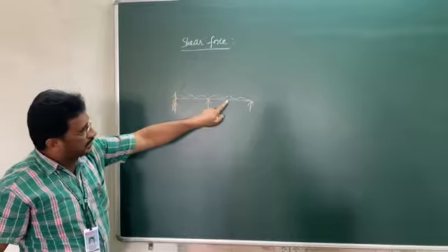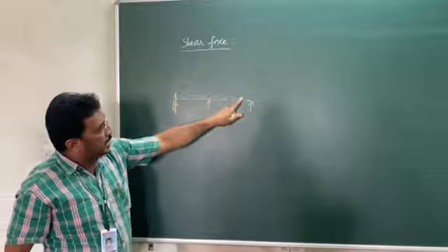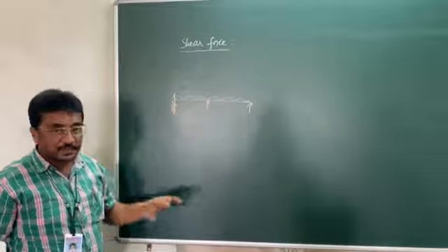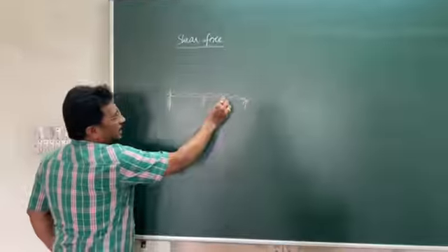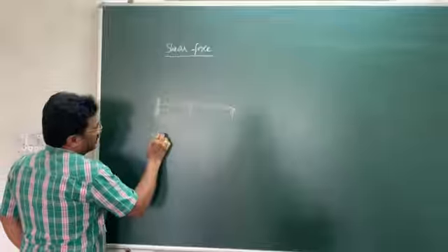But whenever you consider any section here, whatever the unbalanced force on the left side of the section is, and similarly the unbalanced force on the right side, is always equal, and the imbalance force is what is called shear force. So the sign conventions.